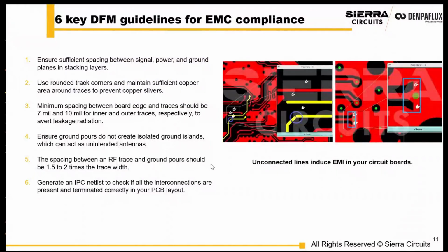Thanks, Vandana. Okay, I have one more slide and then we'll pass it over. So here, we just wanted to summarize some key DFM guidelines to ensure EMC. So as mentioned before, you want to ensure sufficient spacing between your signal, power, and ground planes when you create your stack up. And our stack up tool will definitely help you do that and follow the best practices.